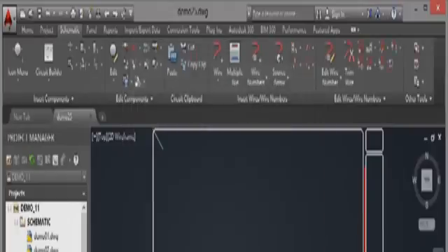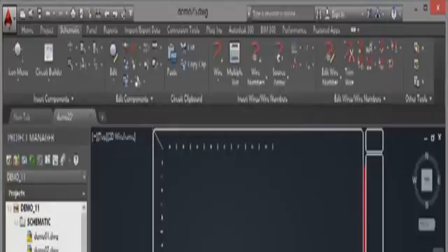So now when I click on OK and then click on OK again, those drawing properties are now set up for that drawing Demo 25, like so. So I go up here now, click on the flyout and go XY grid setup. I go insert XY grid labels, horizontal count, vertical count. Obviously there's 8 and 8. Click on OK, and there they are there.